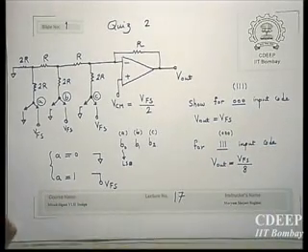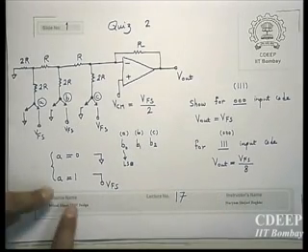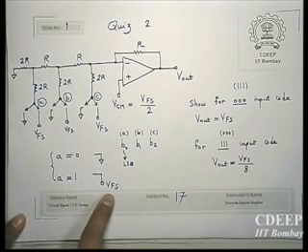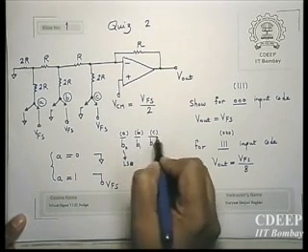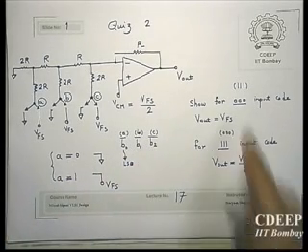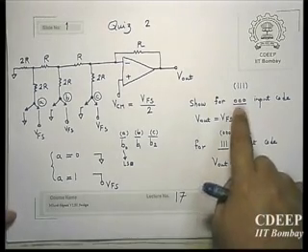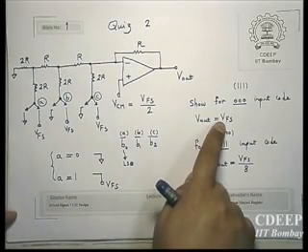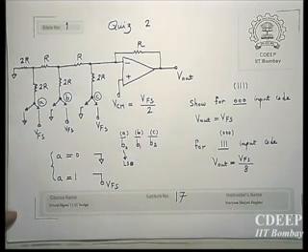It means that these bits are actually the opposite or complement of your bits. Or you can change this order. That would be the same. But because 0 is equivalent with 0, 1 is equal to V full scale, I don't change it here. I just put a bar here. Therefore, don't be surprised why for 0 you get V full scale, for all 1 you will get V full scale by 8. So the point is, when you have 000, meaning all inputs are connected to ground, you will get V full scale. This corresponds to 111, and these bits are the complement of the input bits.